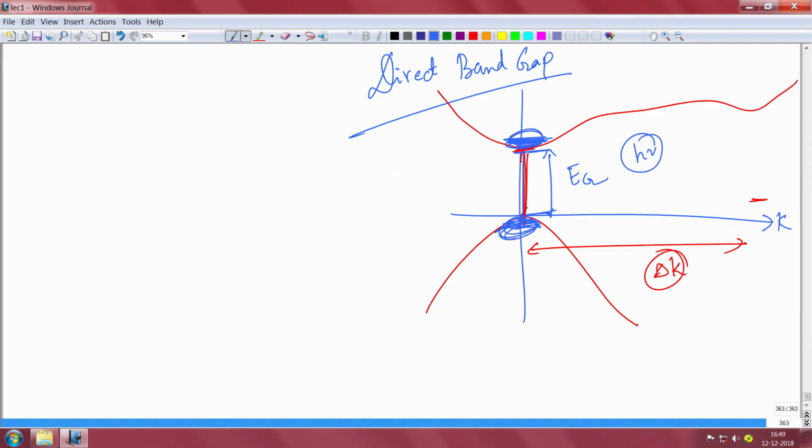At room temperature, any temperature T, there will be a distribution and there is a thermal energy associated with it. So that's why the energy of the photon emitted is slightly more than Eg, very slightly more than Eg. You get my point, right?